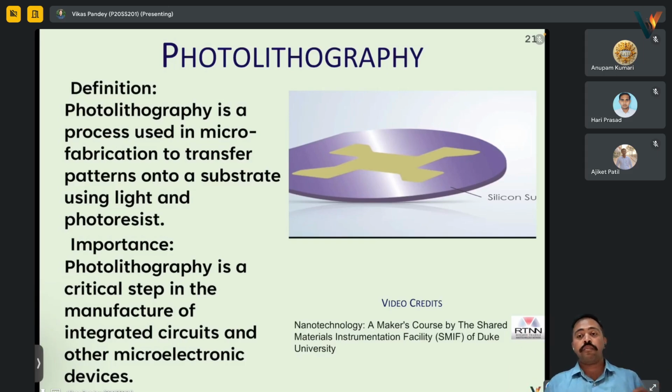So instead of doing it like this, in the first pattern we keep some extra part. We made half of the patterns and kept some gold in the area for the other patterns that we want, instead of clearing it, and that will be cleaned or patterned in the next level of lithography.